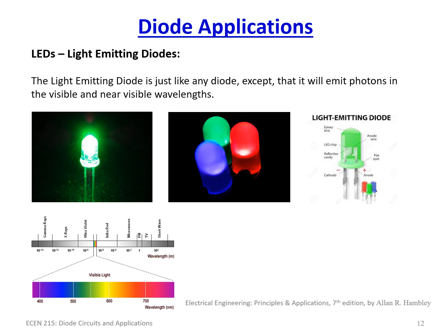They have a VD. They are forward biased. If you forward bias them, the brightness of the light is usually proportional to ID. So as you increase the current going through the diode, it gets brighter. So you can actually change the intensity of your backlight. For instance, all that's happening is your microprocessor in your smartphone is changing the average current that's going through the LED.